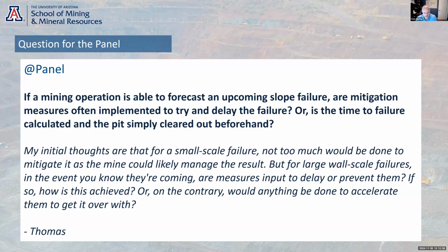But I would say if we have a history that points to an impending instability, we often want to try and do something about it. We're engineers. We don't want to just sit back and be passive. We want to try to be proactive. So in my experience, it doesn't always work, but it's certainly worth a try. And we use lots of different tools in our toolbox. That could be drainage, it could be offloading, it could be buttressing, it could be managing surface water. There's lots of tools in our toolbox that we would probably want to try before just sitting back and letting it happen.